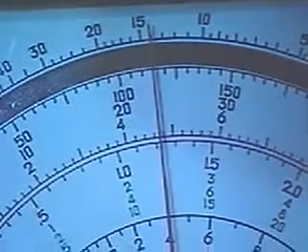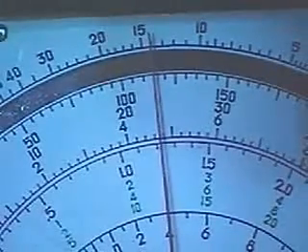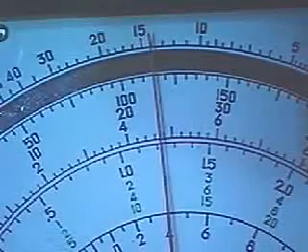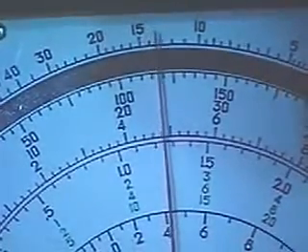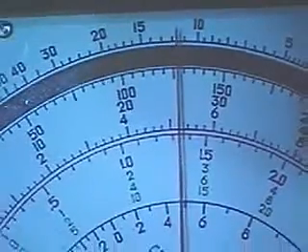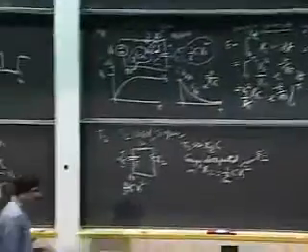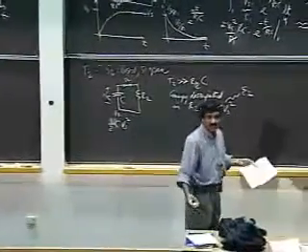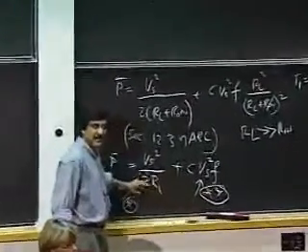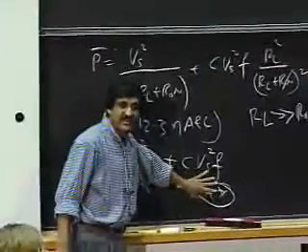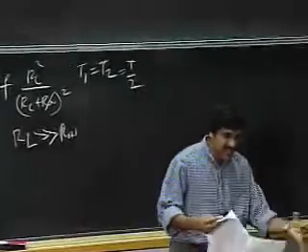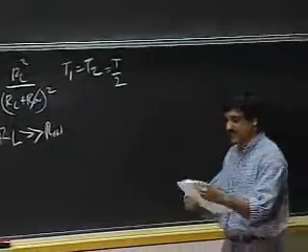Notice that I've increased the frequency by about a factor of 2 or 3. And notice that the needle has moved to the right. I can keep doing that, and the needle keeps moving to the right as I'm consuming more and more power because I'm driving the inverter faster and faster. That should convince you that there is a standby power, and there's some power component related to frequency. This relates to your standby power in your cell phone. This relates to active use. So let me show you some numbers, and you can plug those numbers in yourself and see how much power this inverter is going to consume, and see if it makes sense.